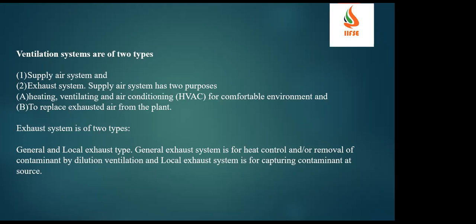In the other way, I'll put an exhaust fan in a room. There I have connected it for the complete room area. I'm not talking about any specific location. There, it will dilute the contaminants. Dilute in the sense it will reduce the concentration. For example, before it is 700 ppm, parts per million. Because of my dilution ventilation system, or the windows or doors which I am having, once I open all the doors and windows, it becomes 200 ppm, parts per million. It has diluted the contaminants. It is the general exhaust ventilation system.